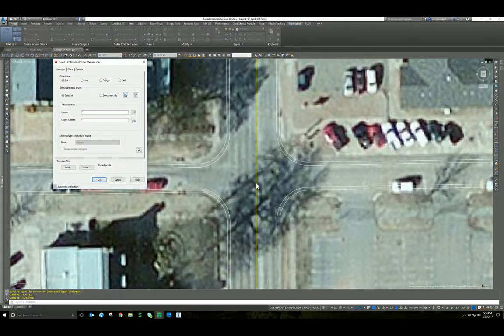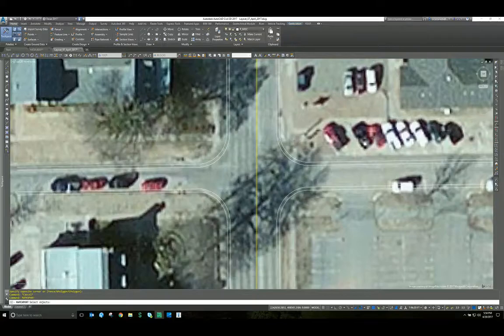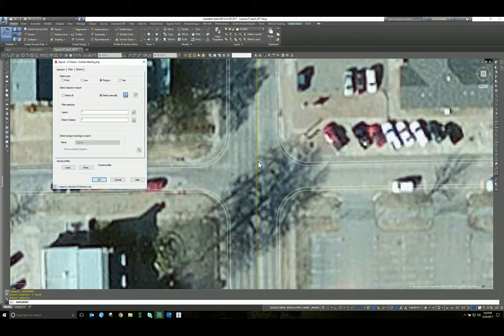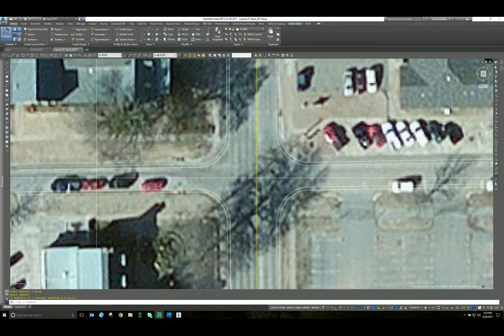So because I know that my polygon is enclosed, I'm going to select polygon, and I'm going to manually select the element. I'm going to hit enter. Now the next step is under options tab, just make sure when you use enclosed polygons that you check the treat closed polylines as polygons. Okay. The next thing for you to check is just make sure that all of the objects selected are not being filtered out. Okay. Click OK.